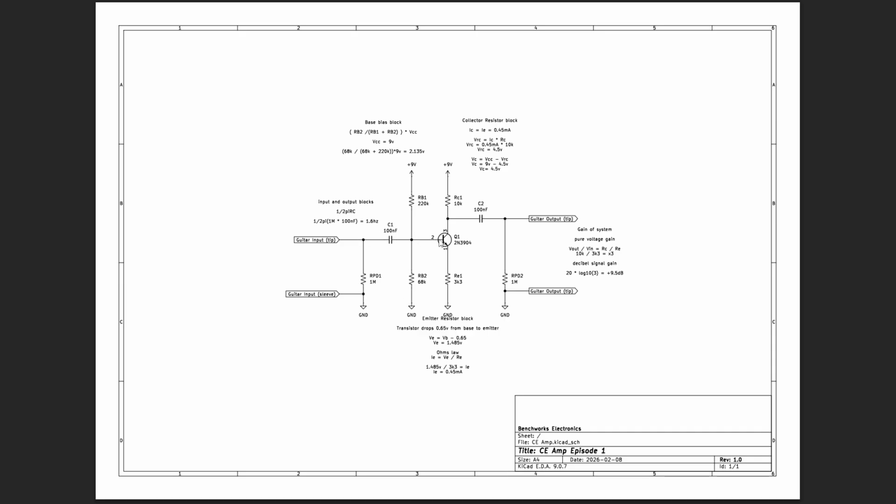So just to recap how we go from pin 2 and how that relates to what we see on pin 1, we have a signal that comes in which has information above 1.6 Hertz in it, and we have power coming down which is 0 Hertz but with 9 volts. So we have whatever our signal is coming in, let's say our guitar signal, and we have some power coming in. The power is contained in this middle section, which is what we want because we don't want it blowing up our guitar or blowing up our amplifier.